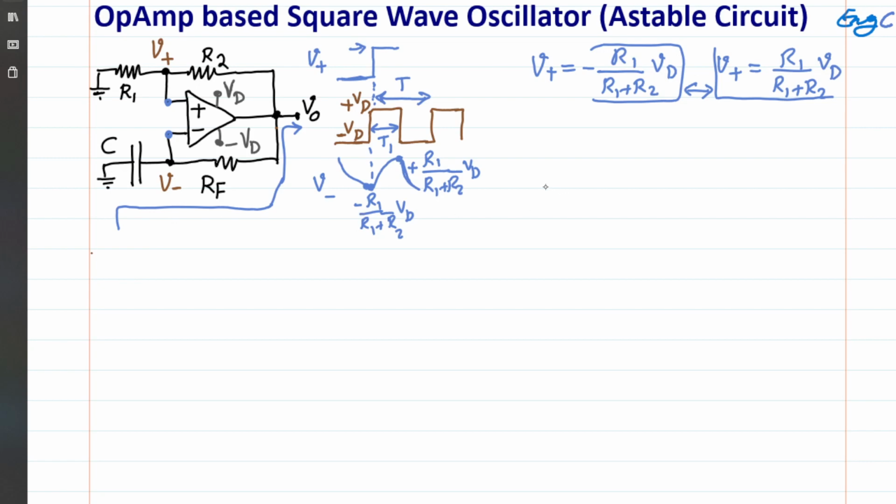From the equation of voltage of a capacitor in a simple RC circuit, it's well known that the voltage of the capacitor at time t is equal to the final voltage of the capacitor, VCF, plus the initial voltage of the capacitor, VCI, minus VCF, times e to the negative t over RC. t is time, and RC is just a constant here, the time constant.